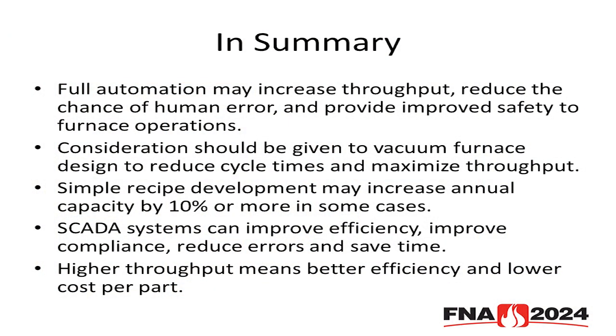It'd be more through the use of work thermocouples and the guaranteed soak function, and then really looking at your dead bands. Do I need it to be plus or minus 10, or can it be a bigger window? And that's how you could maybe optimize it when you have mixed tools. And that's something a lot of people run into, because especially commercial heat treaters, they run whatever they get in. If everything is similar alloys, maybe different sizes and geometries, it's going in together if it's at a similar critical soak, and that would be the way to approach that.